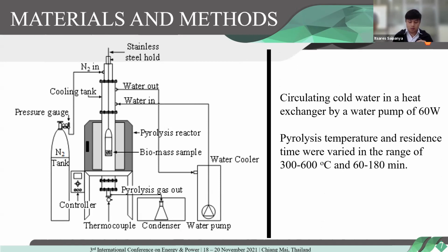In order not to overheat the electric heater, cold water is circulated in the heat exchanger by a 60 watt water pump. Pyrolysis temperature and residence time were varied in the range of 300 to 600 Celsius degrees and 60 to 180 minutes.